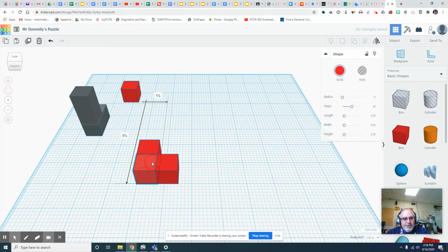Put it so it's inside that first cube there, but then you want to see this little black cone. That black cone will allow you to move parts up and down. In this case, we want to move it up, and you want to watch carefully how high it's being moved, because we're going to move it 3/4 of an inch up. There. Now, because we moved this cube, it's going to be a better idea to copy this cube and then keep pasting from there. It's on the right level, rather than try to copy one in, then move it a lot more. As you just saw, we used the black cone to move this up another 3/4 of an inch.